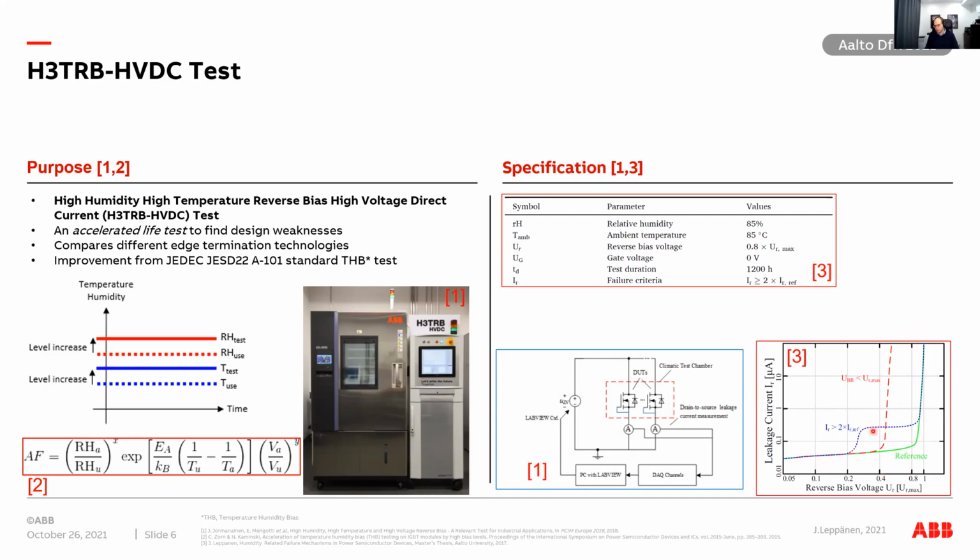So this is what you have to remember, that this is the first sign of deterioration. But obviously the leakage current monitoring during the test is always important. But it tells us the leakage current at one certain voltage level, because we cannot have multiple voltage levels during the test. So it only gives you one point from this curve.